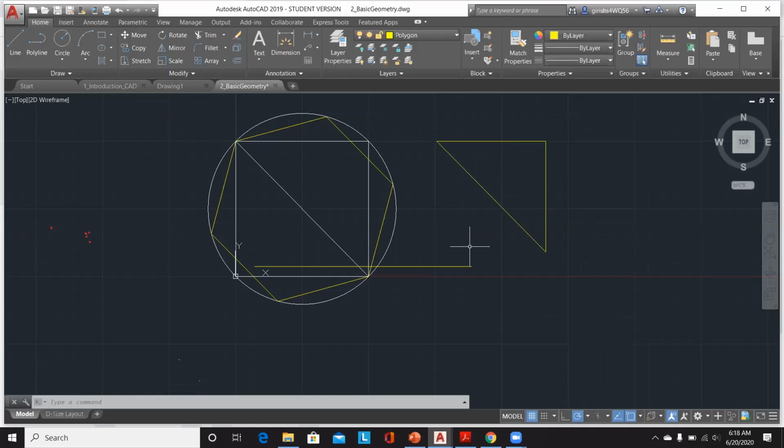When you are in your AutoCAD model space, towards the bottom right corner of the screen is the customization toolbar that we discussed. If you hover towards the left side, you can see a rectangle, and above that a small rectangle, like a snap. It helps you in snapping the cursor to the 2D reference point, and I have turned it on. So if I turn it off,